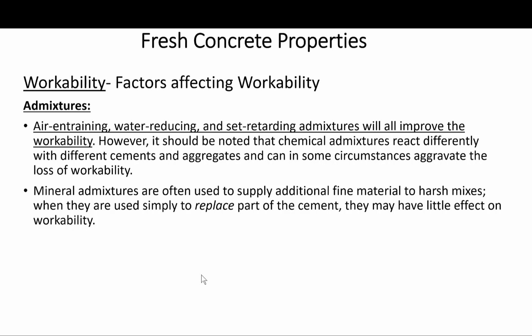There is no other way. As we said, mineral admixtures are often used to supply additional fine material to harsh mixes. When they are used simply to replace part of the cement, they may have little effect on workability. But if they are used to provide basically fines to the mix, it's a different story.